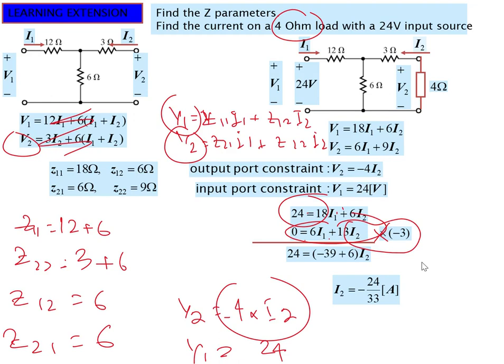This is how we use these parameters. This one is easier than the previous one just because this circuit is simpler for impedance. If we do the same circuit with admittance, you will see that one extra resistance comes in, because in admittance you will make this thing short, and by making this thing short, these three have to be considered now. So this is the difference. Just remember this and we will use it in the future.